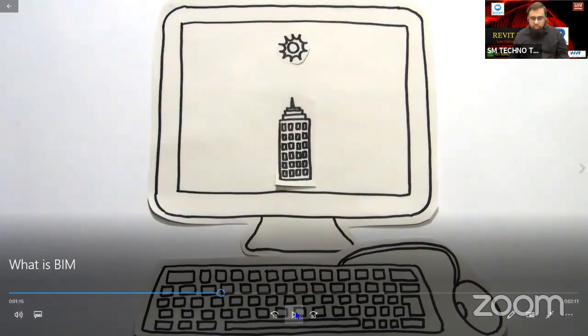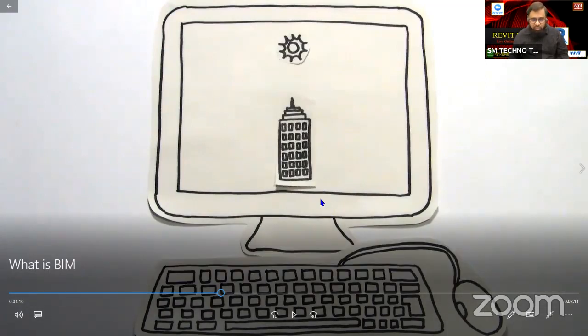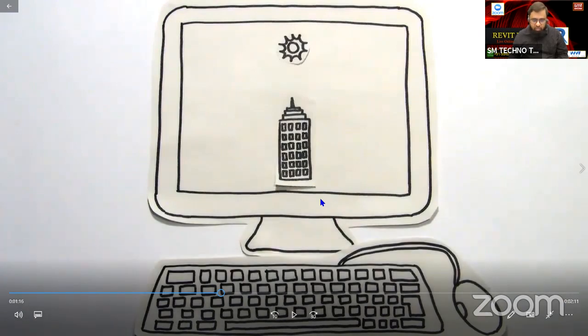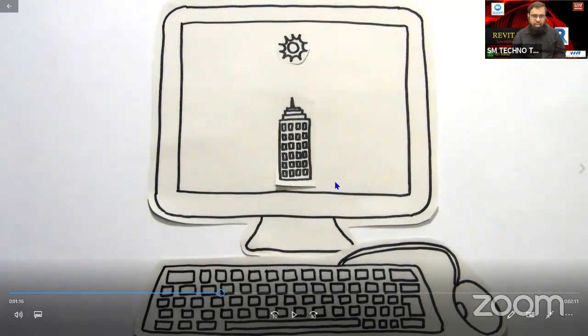You see, this point is important for mechanical engineers, those dealing with HVAC. So you know the importance of heat gain due to radiation. When we are dealing with Revit, followed by this BIM concept, we are dealing with the actual location of the building. And with the location, the software can extract the latitude, longitude, elevation, and even orientation. And as a mechanical engineer, if you know load calculation, you know the importance of these parameters. So we are working with an actual location with all these parameters, which is important for the load calculation.